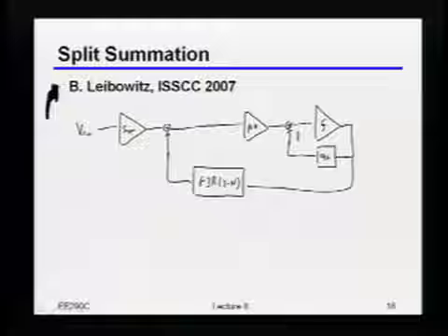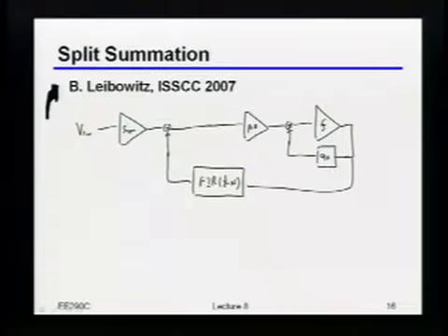So what is that label? Say that again? The labeling. The label, I just said it's 2 through n, meaning that it's taps 2 through n rather than the very first tap. All right, so in other words, there's at least one delay in this FIR filter here before you correct all of the residual ISI.